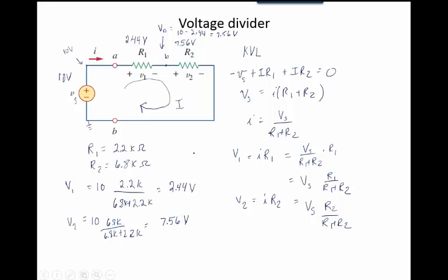So did you see that there's 0 volts all the way from R2 back to the... Well, the potential that's here is the same. It's constant. It didn't change if you assume ideal conducting wires with no resistance whatsoever. This voltage is constant here. So if this is tied to ground, then all of this along here is at 0 volts.